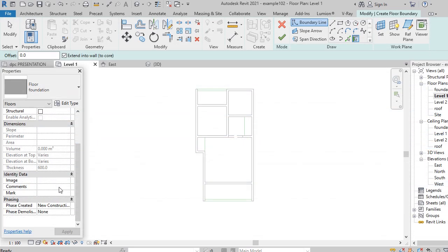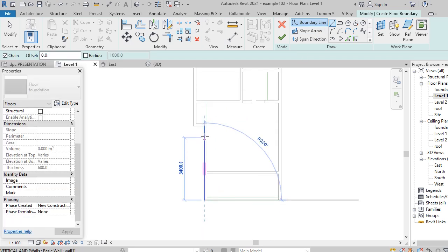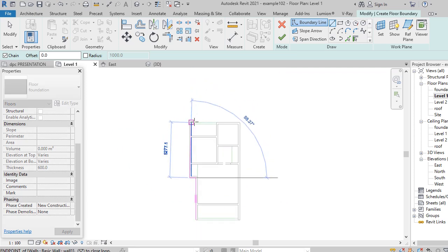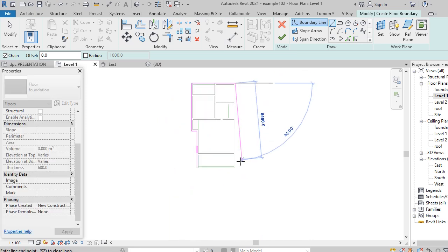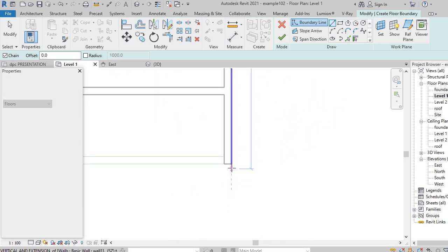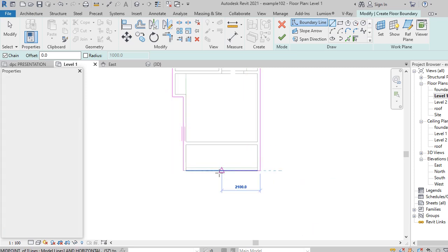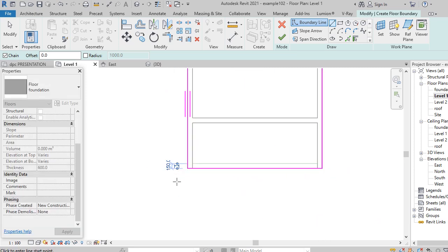So thickness 600. Then here you can either pick your rectangle or your lines. Now we don't need rectangle because we have a recess at this point. So let's just choose line, and you come and make your line from this point to this point. Also take note that in any sketching you're making, Revit will always allow or encourage a closed loop.